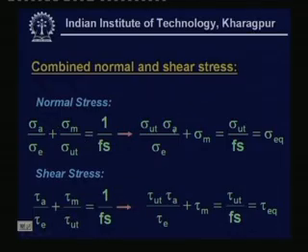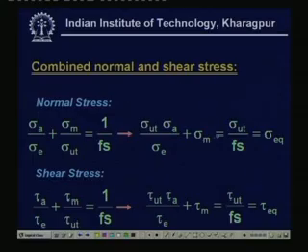With a little manipulation of this equation, you multiply all through by sigma ultimate, and we get an expression of this type. Now, if we identify this factor, you can easily realize that sigma ultimate by factor of safety is nothing but the concept of a design stress.